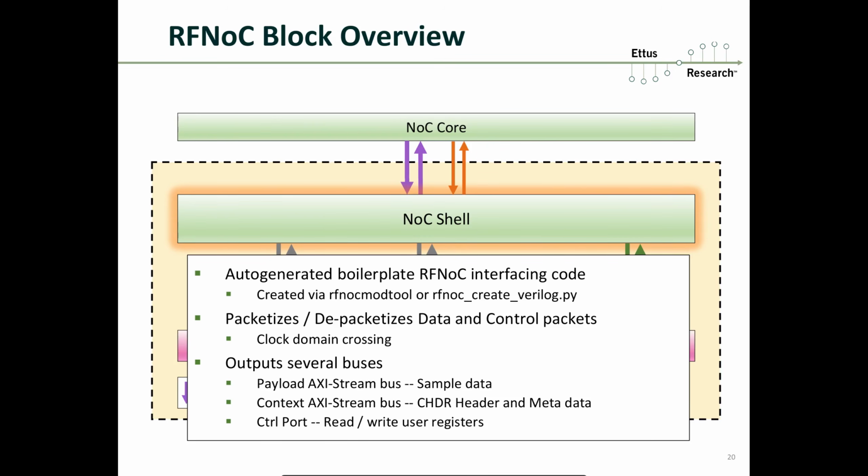The nice part about rfnoc-modtool is that it creates this whole directory structure with all of your YAML files and the other files that you need, automatically. rfnoc-create-verilog expects you to already have created this block description YAML file, which we'll talk about later. But if you're new to RFNoC, you may not know what this file is, or how to fill it out and specify anything. So that's why rfnoc-modtool is a bit more approachable, especially when you're very new with RFNoC 4.